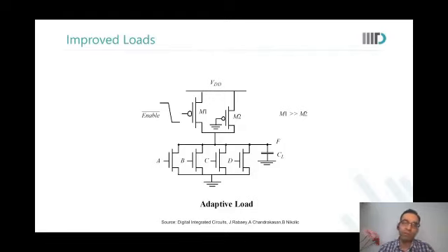Is this point clear to everyone? So, sir, in effect, with this effort, we are trying to make the delays again the same, like the rise delay equal to the fall delay. Yes. That is what our attempt is, that rise time and rise delay and fall delay should be almost equal, because if they are not, then at a system level, you have to put in a huge penalty in terms of managing setups and holds. Yes, sir. Because earlier the fall was already less, so we had to make it equal. Okay, sir.